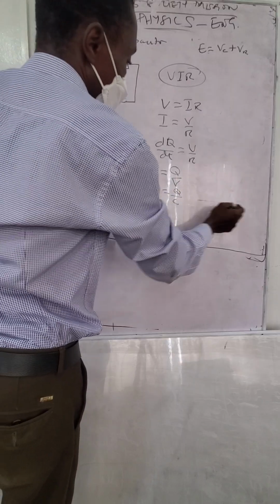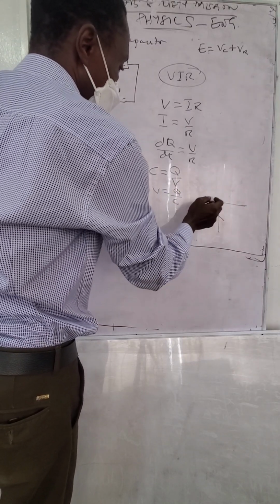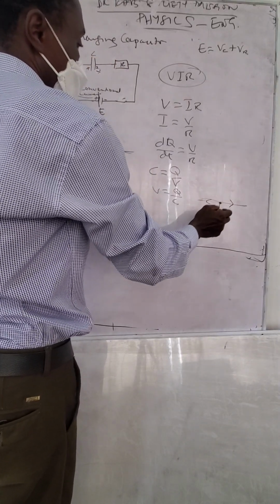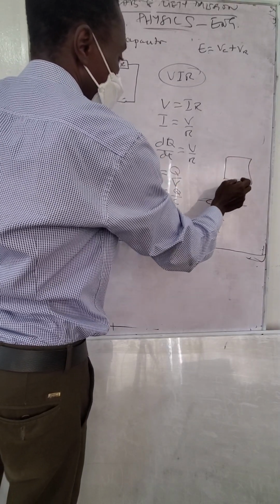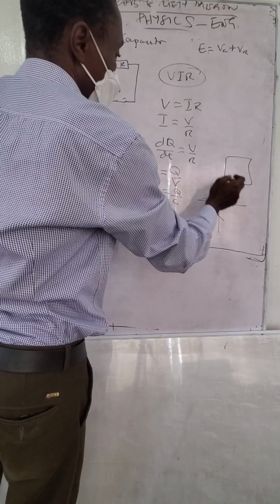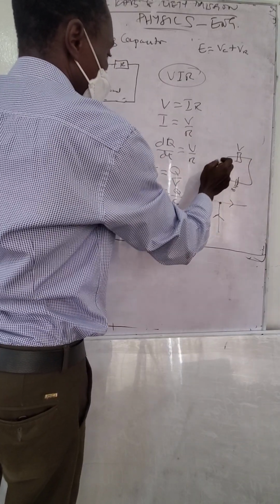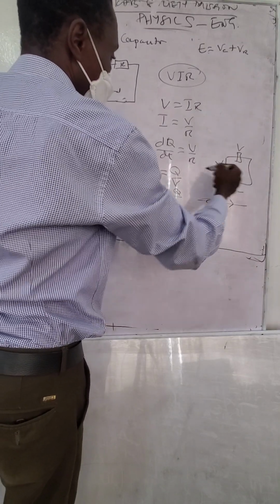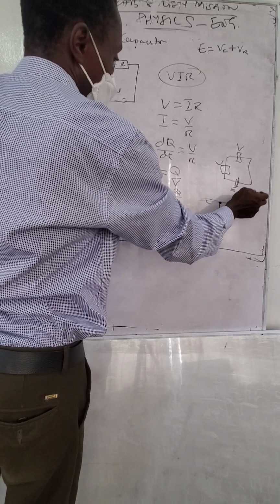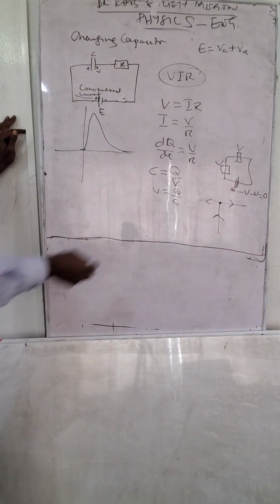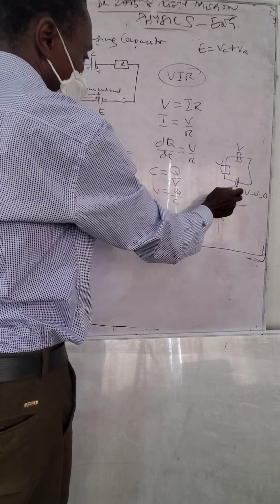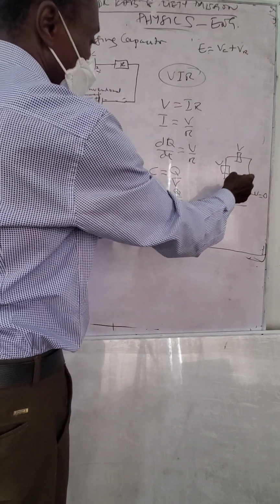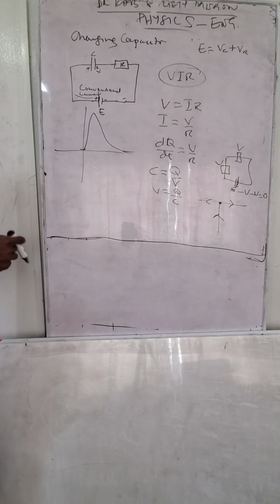The other one is that at a junction, the current coming in should be equal to the current leaving. And then in the closed circuit, this is my EMF. This EMF must be equal to this and that, or the sum of the various EMFs should be 0. So if you add all the EMFs, it should be 0. This is the source, so if it is positive, these ones are taken from it. You take a direction, and the direction can be used to do the calculation.